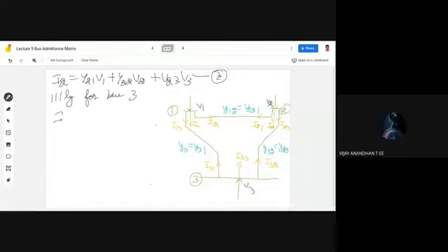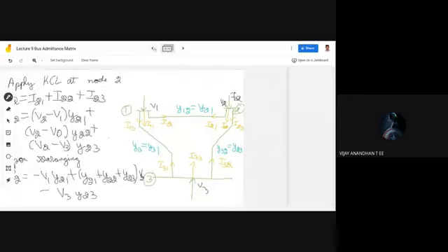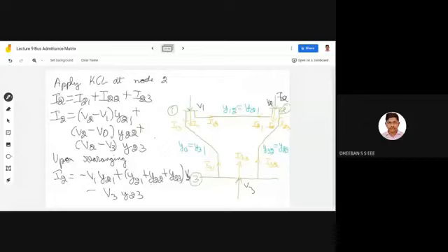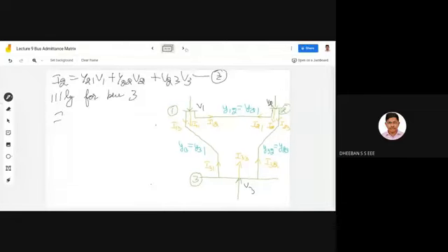For minus y21 and minus y23, you will rewrite them as capital Y21 and capital Y23 as well. For self admittance only, you have to go for summation. Otherwise, this corresponds to a transfer admittance, and for transfer admittance you can directly write it. Over here I forgot to say that for the transfer admittance, you have to take a minus out.